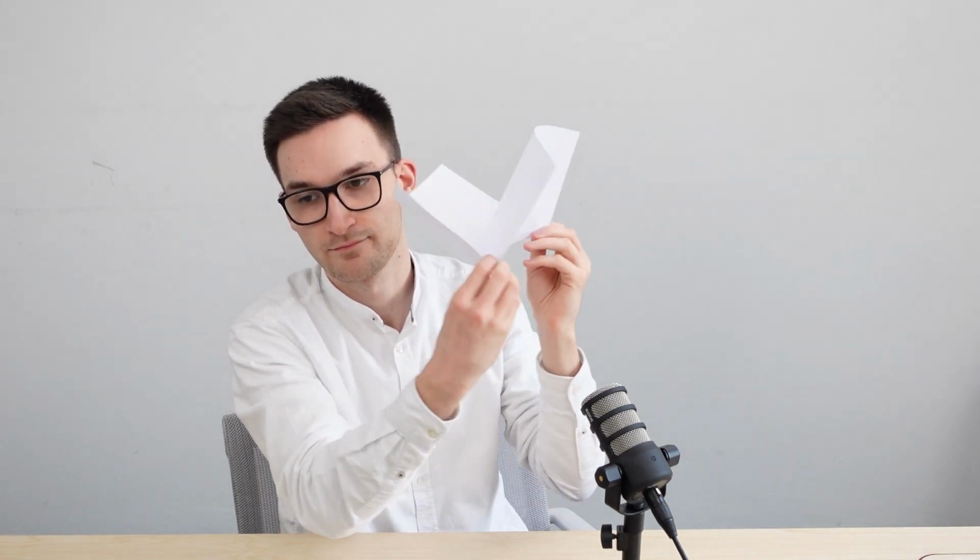The table can be described as a reflection plane. If you measure the angle of incidence and reflection on both sides, you will notice that they are identical. A very important observation can be made by increasing the degree of the arc or decreasing the radius of the arc. There is therefore a relationship between the degree of the folding curve and the angle of the folding. This is one of the most important aspects to consider here. With this knowledge you can now create complex shapes.